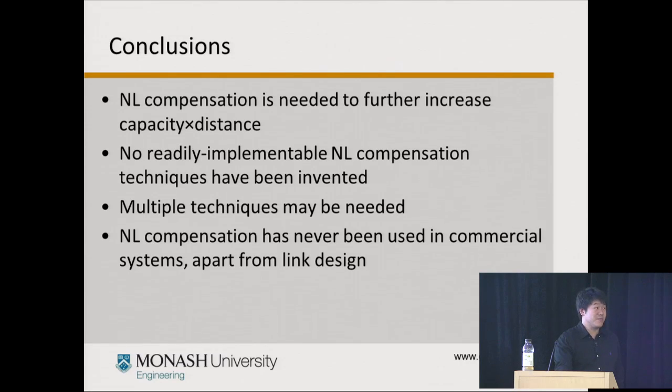Having said that, Google people might know this better than me, so I might be wrong here, but to the best of my knowledge, nonlinearity compensation has never really been used in any commercial systems. Apart from using intelligent link design, like in the case of NRZ, or indeed in the coherent case, where you're taking the DCF out, for example. Apart from that, we really haven't implemented specific techniques to improve the nonlinearity performance.